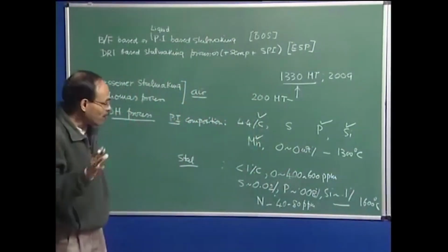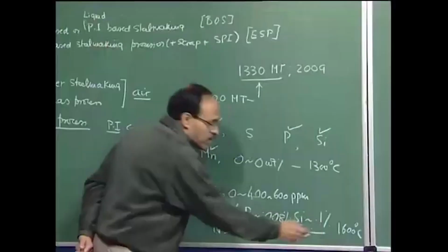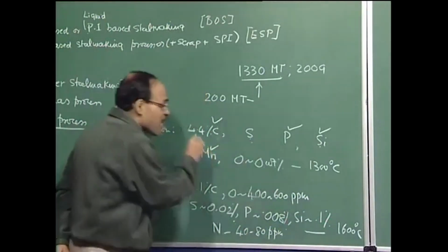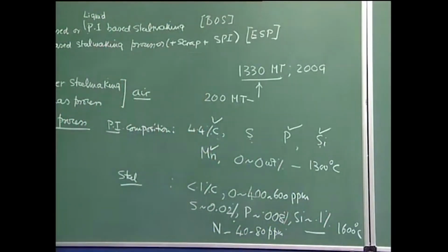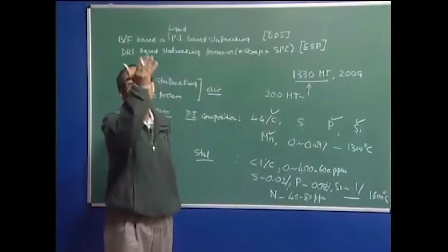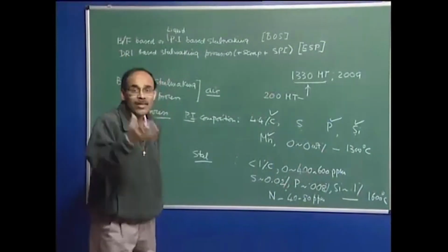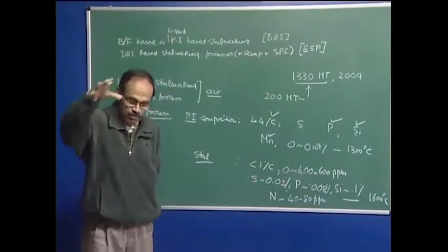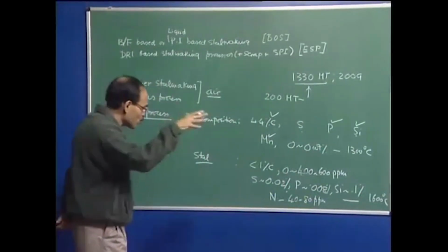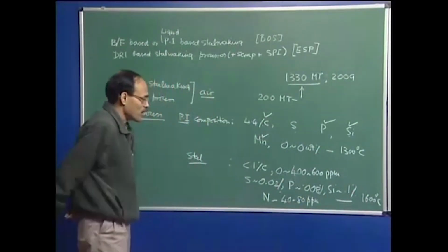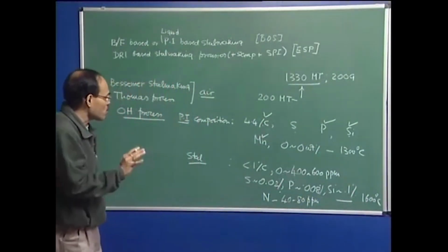Otherwise, it will be very difficult to bring it to 1600 degrees centigrade. Often in steel making, the level of contamination is such that the temperature gets even higher than 1600 degrees centigrade. In such a scenario, we add coolant into the steel, which is nothing but plant-generated solid scrap. When you put that solid scrap into the steel making reactor, the temperature goes down.